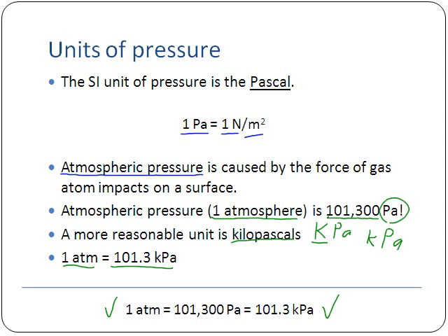We're going to see a number of different units for pressure here. Keeping up with this and writing it on one of your colored sheets, if you've got it, is going to give you a way to convert between your units. So this is a little bit important as we go through here. This is what we have so far for units of pressure: one atmosphere is 101.3 kilopascals.